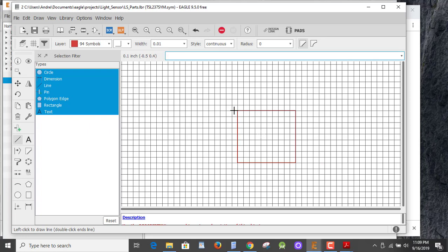And this is exactly what's going to appear. I'm hitting the escape key. So this is what will appear on the schematic, and so this is 1, 2, 3, 4, 5, 6, 9/10 of an inch high and about an inch wide. That seems like it'd be an okay size on the schematic, about an inch by an inch. And I'm going to put some pins on this.